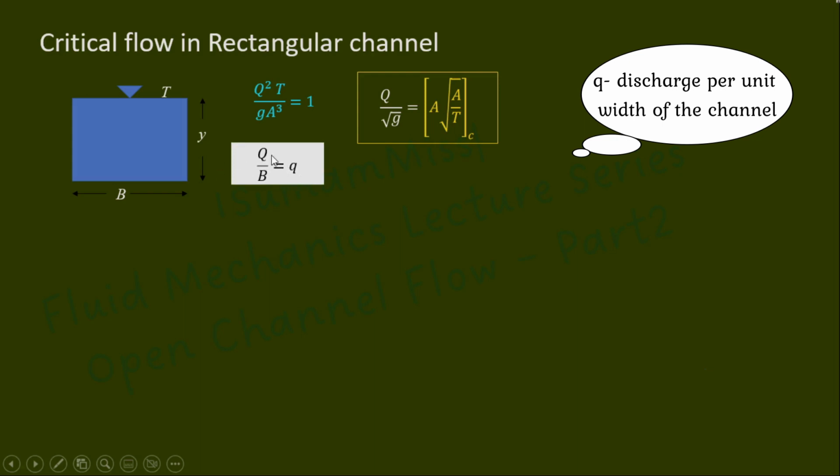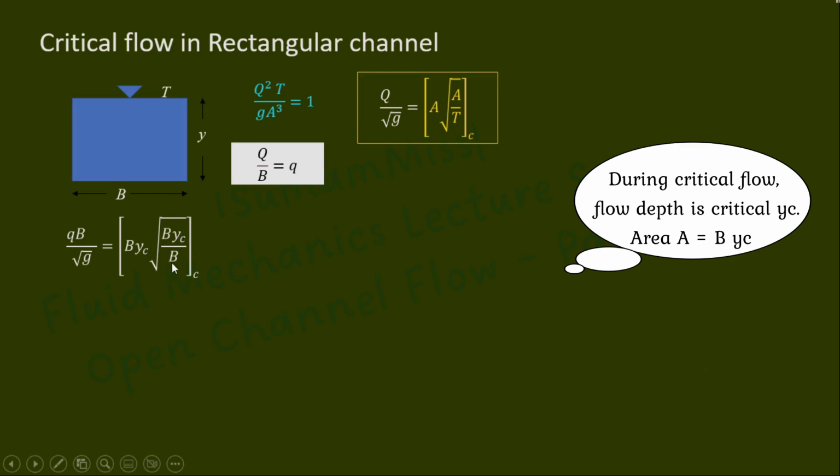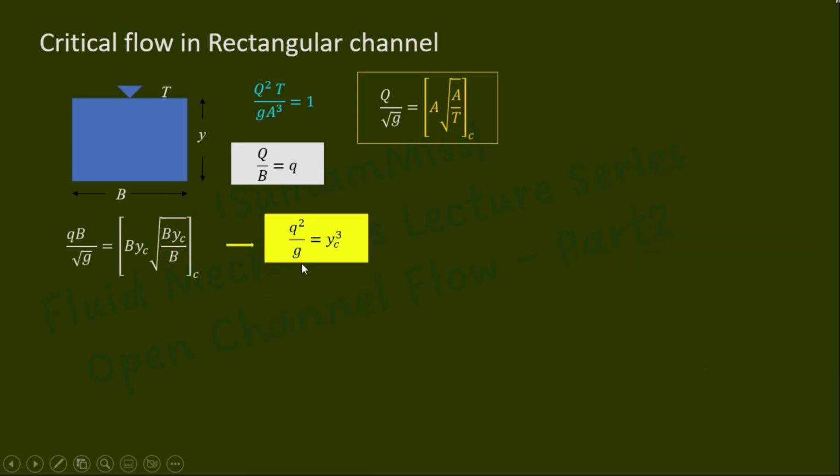So if you represent capital Q equal to q into B and substitute in this expression, you will get QB by root g equal to A, which is represented by B into yc into root of B yc by B. Simplifying this expression, you will get q square by g equal to yc cube, or critical flow depth equal to cube root of q square by g. Remember, this expression is valid for a rectangular channel, where q represents the discharge per unit width.